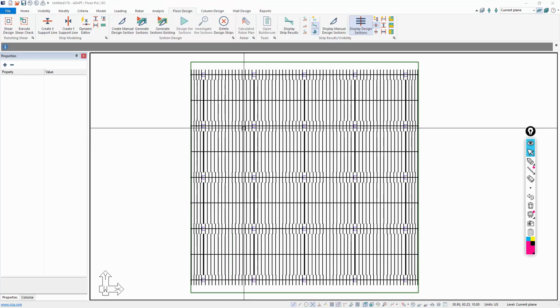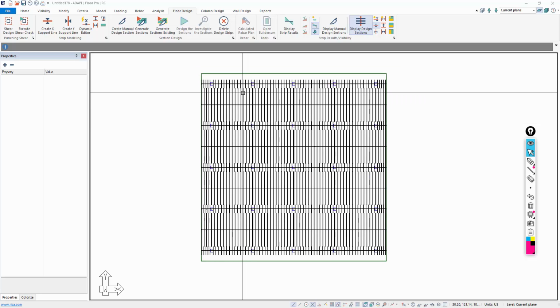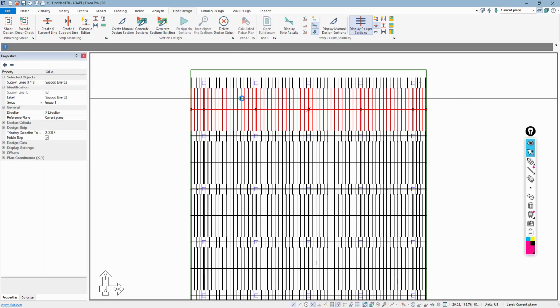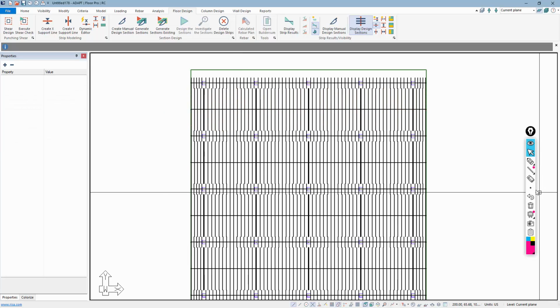Okay, and that outcome is, again, this distance from the support line on the column strips, which was set to 3-foot max per side. This is limited to 3 feet. So because this is a middle strip tag, the middle strip, it doesn't matter what the dimension is from here down, it will always fill in the gap between the two boundaries of the column strips if it's tagged as middle strip. That's the key.